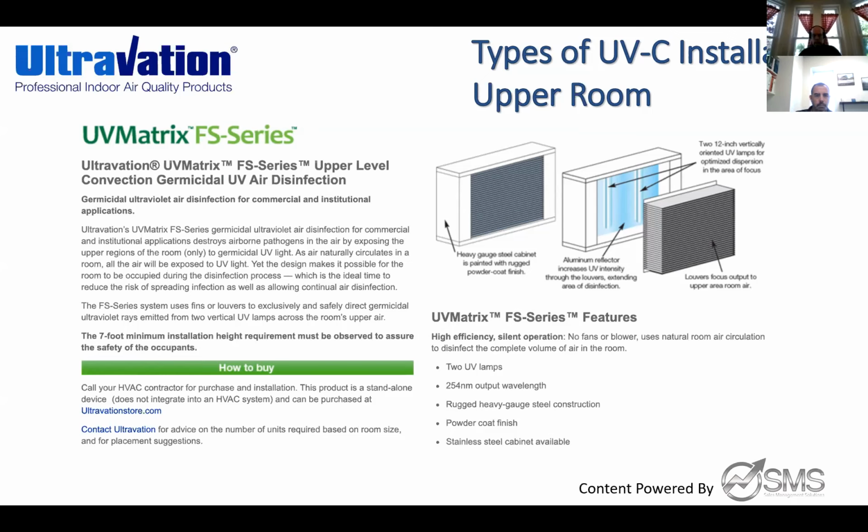Something like this is going to be good if you do not have ductwork running through a building. If you just want to add extra IAQ in a room, this is primarily for commercial. I guess you could use it for residential, but this is typically going to be used in a commercial setting. You'll see Scott is hovering over the 7-foot minimum requirement for installation height. That is very important to adhere to for safety.